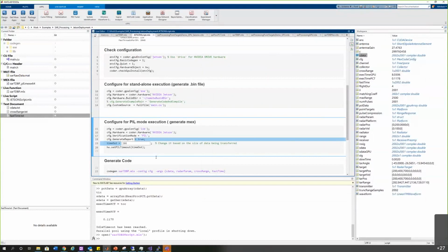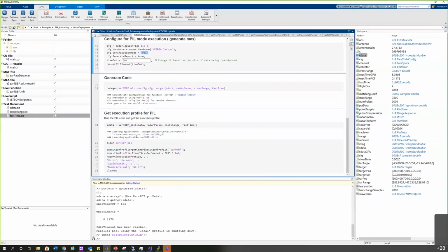What it means is that if the data is coming in live, as the sensors are acquiring the signals, it is going to be processing live, and then I'm getting the results. That is embedded deployment. But at the same time, before doing this EXE, we also have the option of processor in the loop. If you would like to connect your GPU device with MATLAB and run it together, in the processor in the loop, you do it for verification and validation.